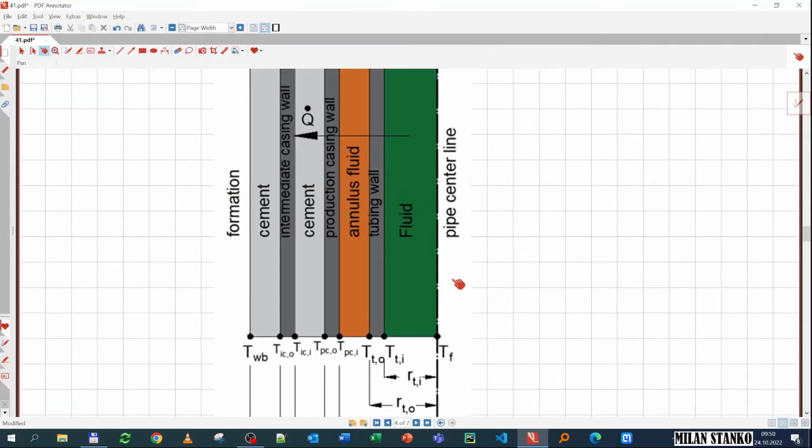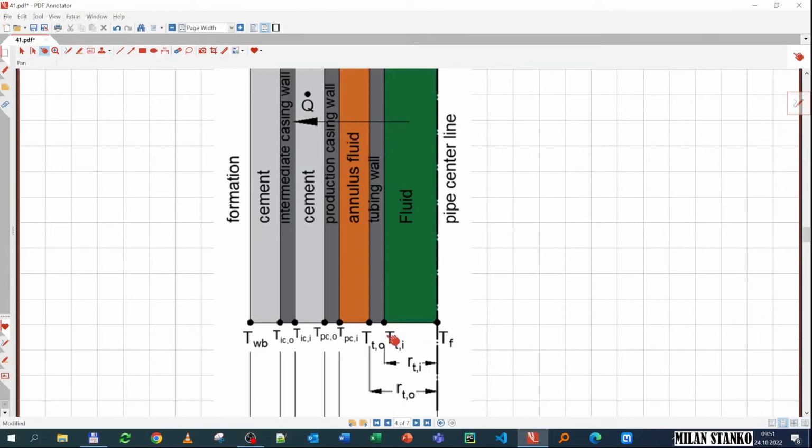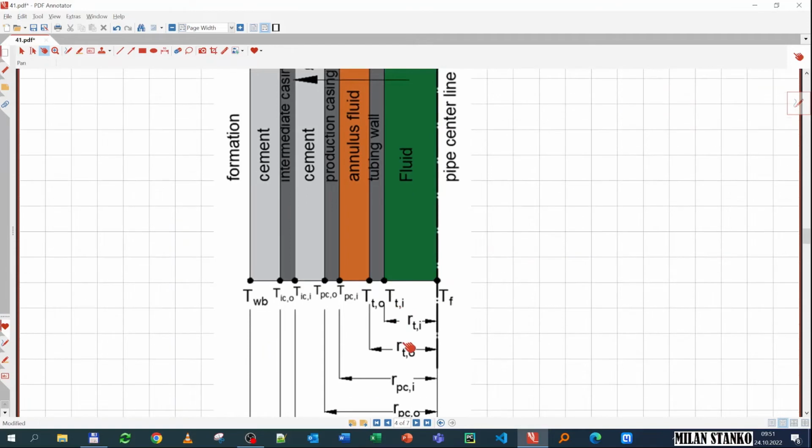Typically our heat term, the Q, we express in terms of TF minus, so the two outer temperatures. So we want to express this Q in terms of that. We can express this Q in terms of each mechanism that we have, for example on each delta T. This Q will be in terms of the forced convection coefficient times the delta temperature here. So we're going to do a trick. We're going to express all these temperature differentials as the Q and the mechanism that is happening in each one of these layers. I'm going to add all of them up.